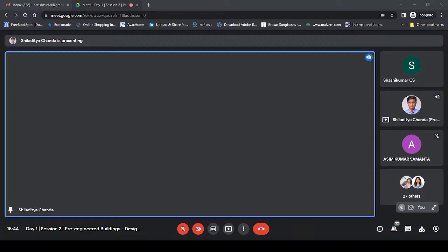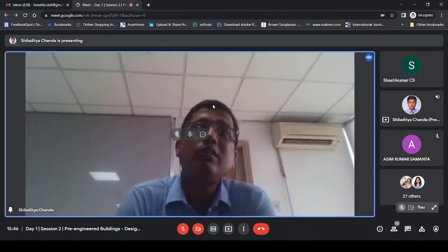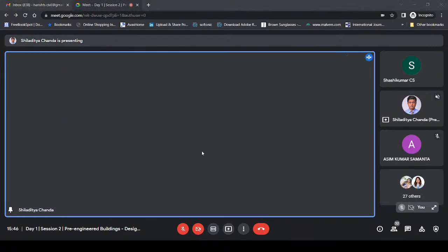Okay. There is a moment in space. You are basically allowing a space frame design to take place. Yes, sir. Which you said is that we need to model separately. I design it separately, or even if it is not a model, I can do it by hand calculation also for bracing. It is simple. Calculate the roof drag, calculate the wall drag, and distribute in two sides and just design this particular bracing system.